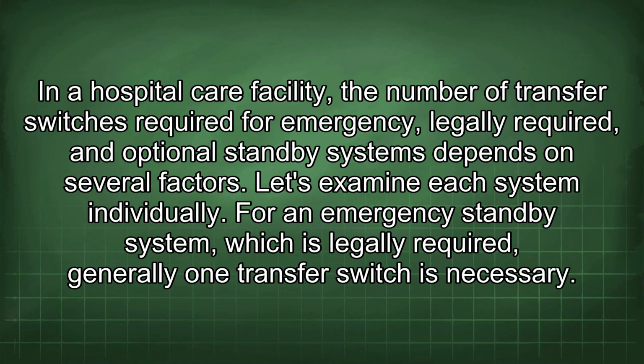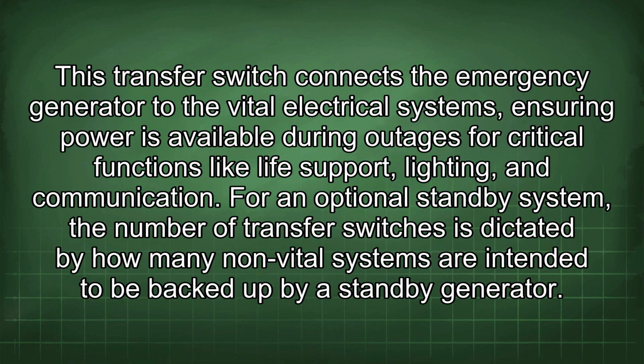In a hospital care facility, the number of transfer switches required for emergency, legally required, and optional standby systems depends on several factors. Let's examine each system individually. For an emergency standby system, which is legally required, generally one transfer switch is necessary. This transfer switch connects the emergency generator to the vital electrical systems, ensuring power is available during outages for critical functions like life support, lighting, and communication.